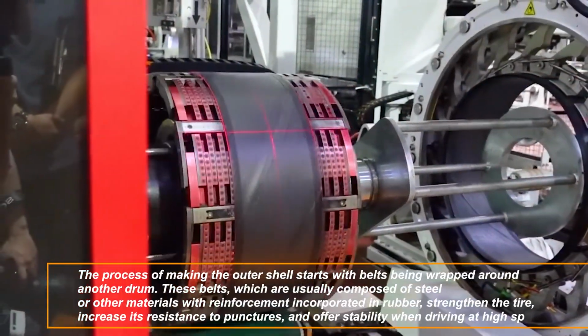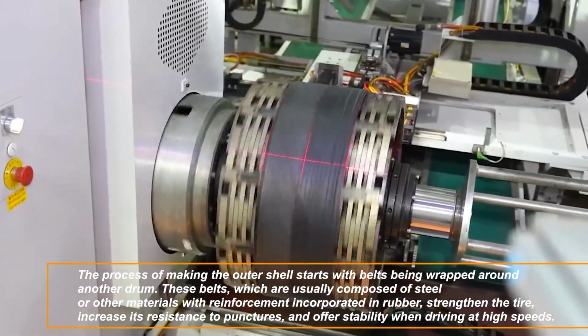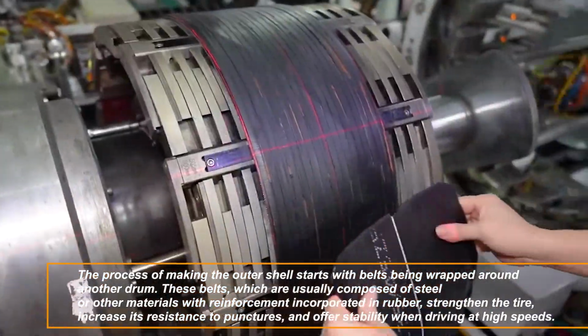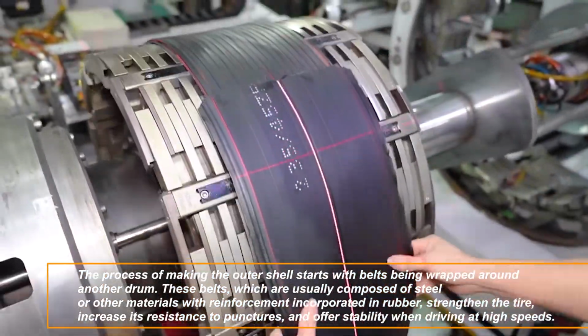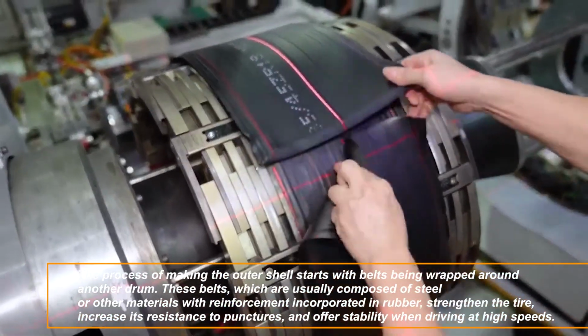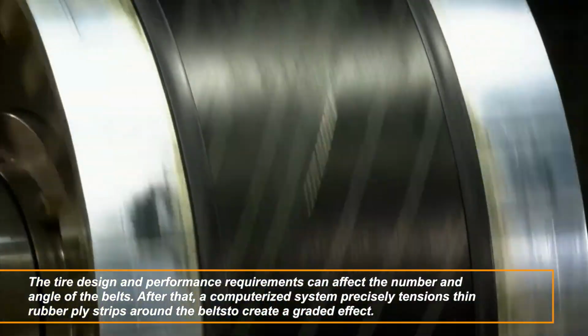The process of making the outer shell starts with belts being wrapped around another drum. These belts, which are usually composed of steel or other materials with reinforcement incorporated in rubber, strengthen the tire, increase its resistance to punctures, and offer stability when driving at high speeds. The tire design and performance requirements can affect the number and angle of the belts.